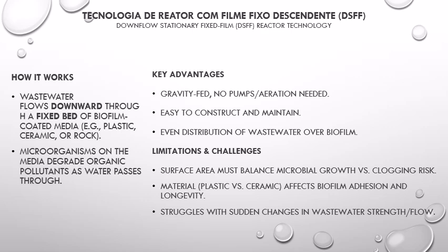Now we can think of this just like a waterfall, whereby water falls through, passing through a bed of bacteria-coated rocks or plastic pieces. That's the downflow stationary fixed film. Now as it passes through, the bacteria there grab and break down the pollutants. Thereby, like that waterfall, there are no pumps needed, there are no bubbles needed, that is, no aeration is needed. So it's a super simple process to build and run. But it actually works best with steady and predictable wastewater.